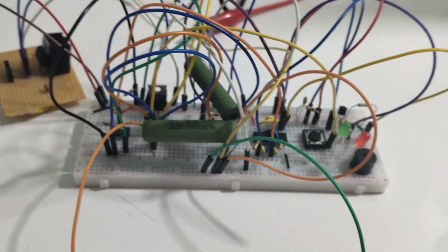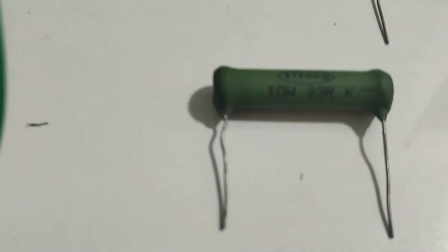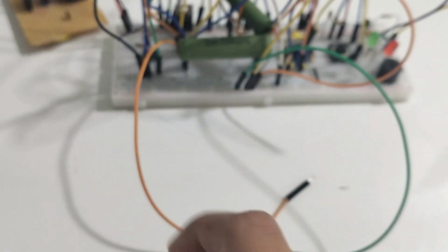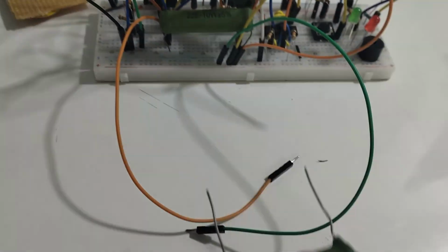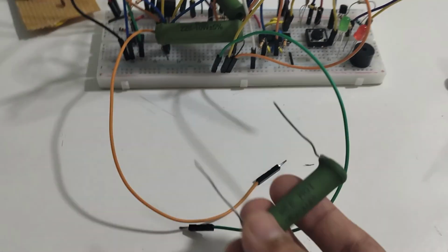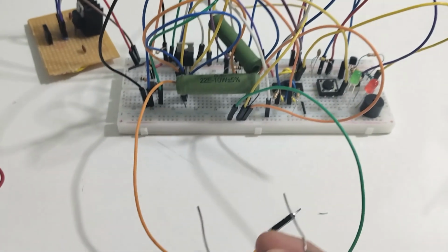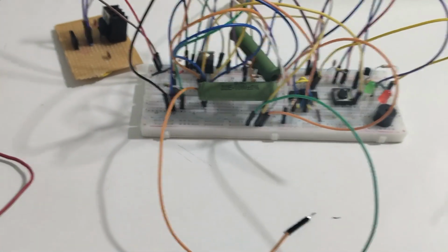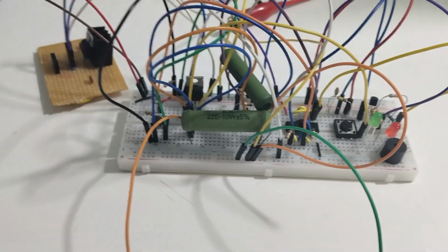To demonstrate the overcurrent, I have another 2 resistors here: first a 33 ohm over here, and the second is a 10 ohm. To demonstrate it, I've pulled out these 2 wires which are just across this load resistor, and if we put this resistor in parallel with this, of course the resistance would decrease. If you put 22 ohm in parallel with 33 ohm, it would roughly be 13 ohms or so, and the final current flowing would be around 800 or 900 milliamps, and that is still below our 1 amp limit.